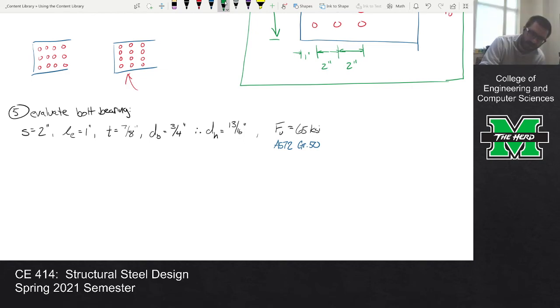Hold on. I'm going to get to Mr. Randolph's question. That's in table 2-5. Okay, Mr. Randolph's asking if there's pitting on a plate, does our effective thickness change when computing a load rating? Are you talking about corrosion out in the field? Short answer is yes.